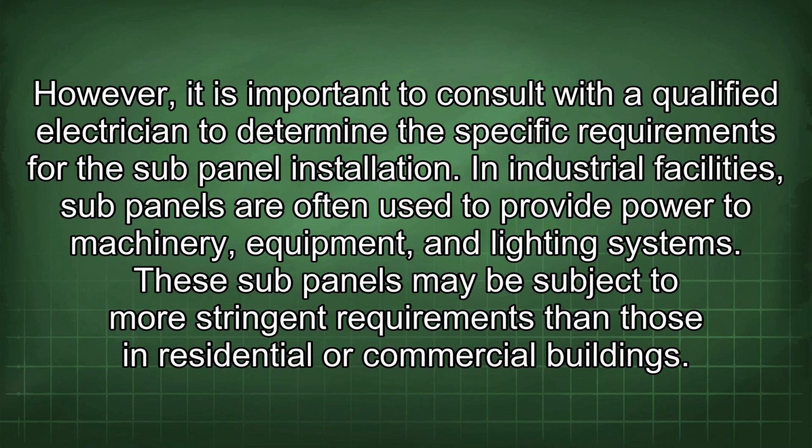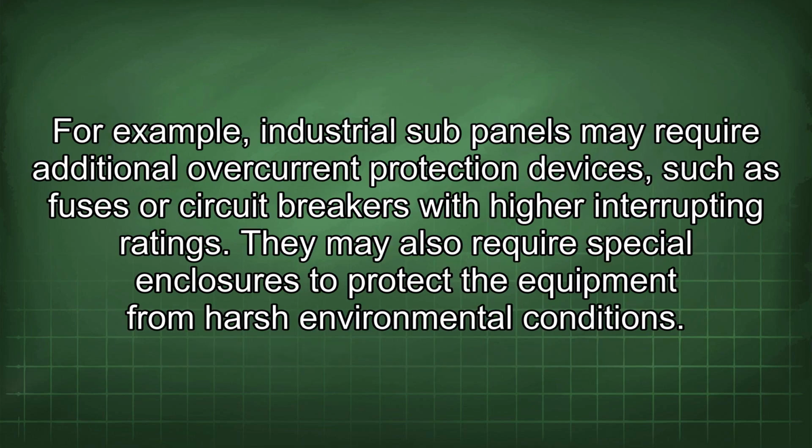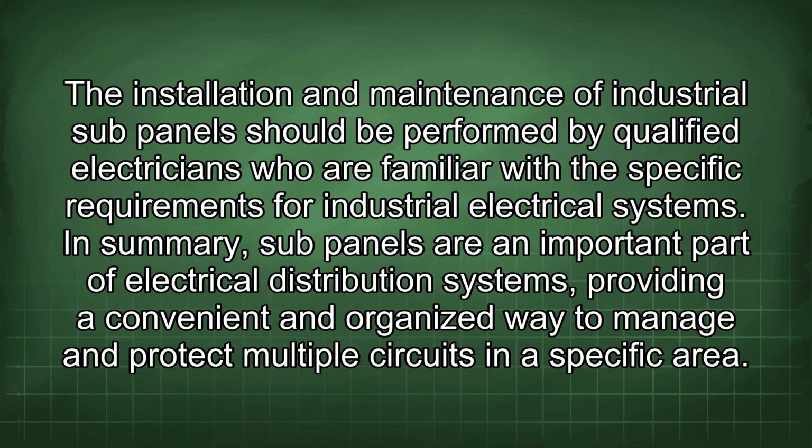In industrial facilities, sub-panels are often used to provide power to machinery, equipment, and lighting systems. These sub-panels may be subject to more stringent requirements than those in residential or commercial buildings. For example, industrial sub-panels may require additional overcurrent protection devices, such as fuses or circuit breakers with higher interrupting ratings. They may also require special enclosures to protect the equipment from harsh environmental conditions. The installation and maintenance of industrial sub-panels should be performed by qualified electricians who are familiar with the specific requirements